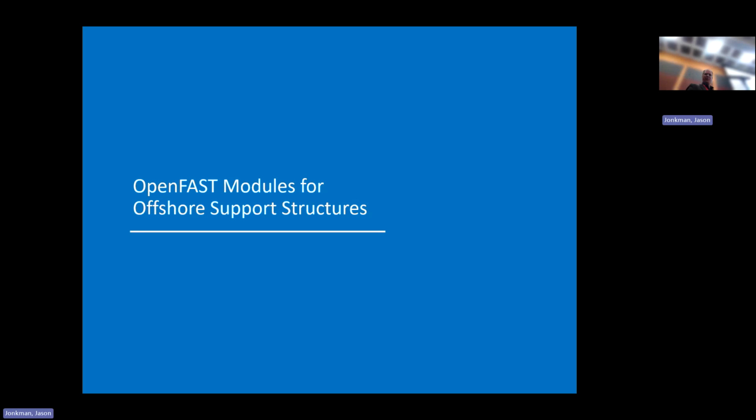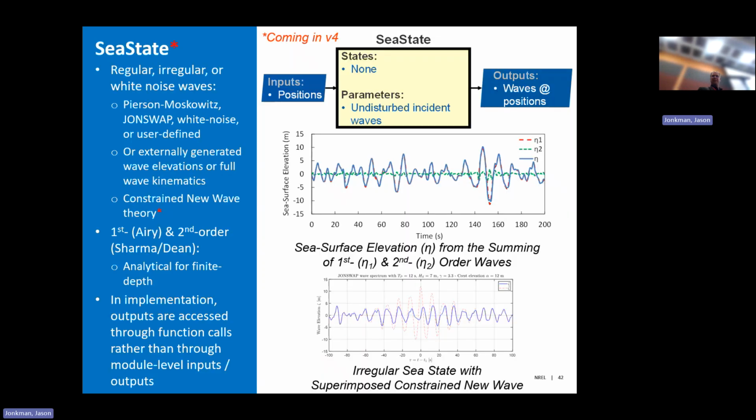Okay, offshore capability. So again, we can do fixed or floating systems. For those of you who've used OpenFAST before, HydroDyn probably. What we did with 4.0 is we extracted SeaState, just like InflowWind is separate from AeroDyn, although you always use them together. SeaState's been extracted out of HydroDyn as now its own thing, but it basically acts like InflowWind for the wind side.